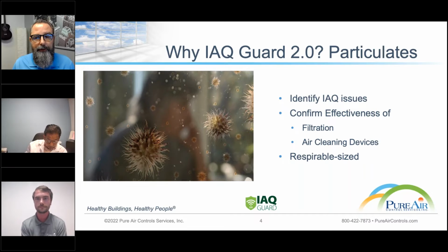But if these filters are filling faster, or if, let's say, there's a deficiency of some sort within the air handler units themselves, they're not airtight, the cabinets are leaking, or the filter rack isn't tight, or the filter might buckle, there might be what's called bypass. This filter bypass can bring particulates in to foul the coils, but some of these smaller particulates can also get into the airstream downstream and affect the occupied space.